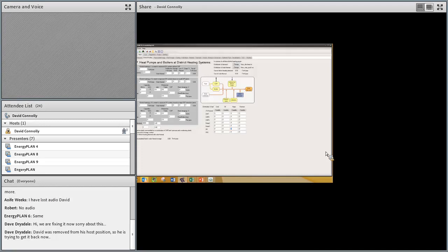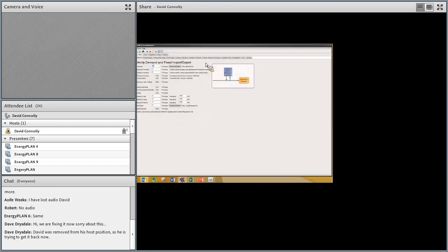I've now installed, you could say, 6,000 megawatts of power plants using natural gas to meet an electricity demand of 20 terawatt hours over the year. This will be modeled on an hourly basis using the default distribution in place. So for example, the electricity demand will use this default distribution here on the right hand side of the 20 terawatt hours. If you have your own distribution, you can click the change distribution button, and from there you can enter your own hourly profile when modeling whatever system you have at present.